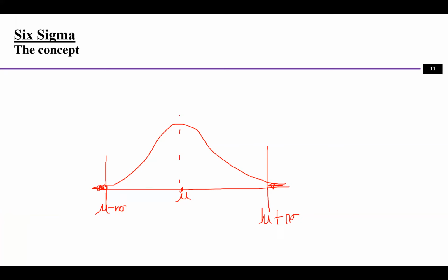This n means how many sigmas away from mu. For Six Sigma, we can tell that the defect probability is a very small number. I can't remember exactly, but I think it's something like a few defective parts in 1 million. This is where Six Sigma refers to the probability of defects in production.